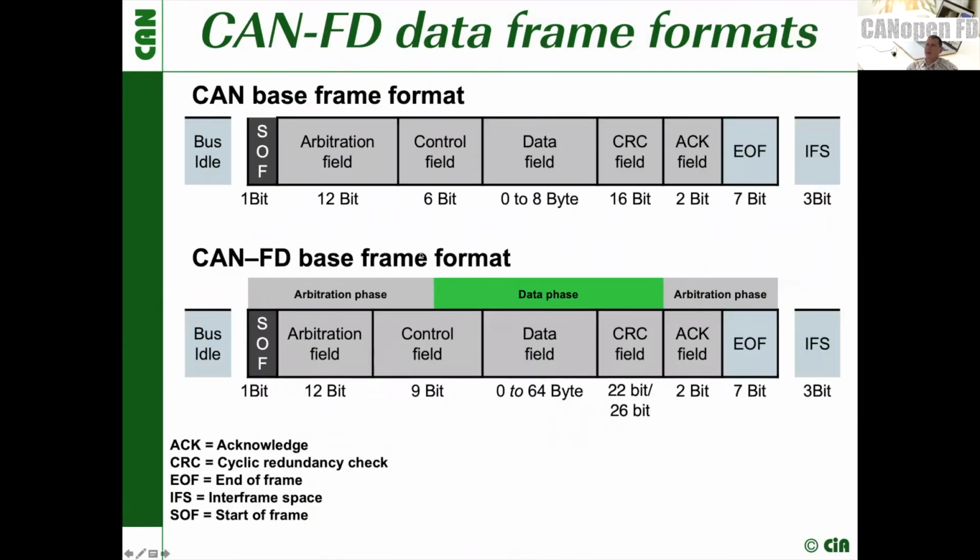And to remind you a bit, on the data link layer, we have a CAN-FD data link layer. This means we now have in CANopen FD the option to transfer CAN-FD data frames with a data payload of up to 64 bytes. And if you like, we can transfer the data field in an accelerated way, depending on the bit rates specified by CANopen FD or some additional ones.